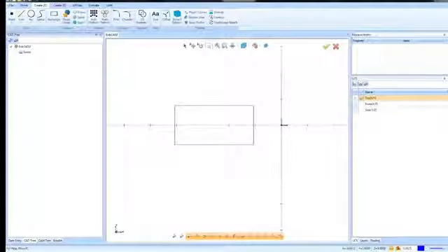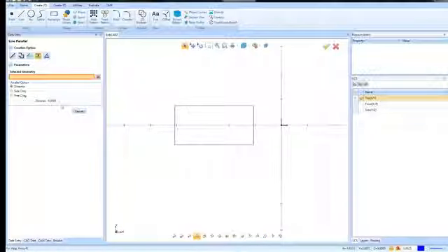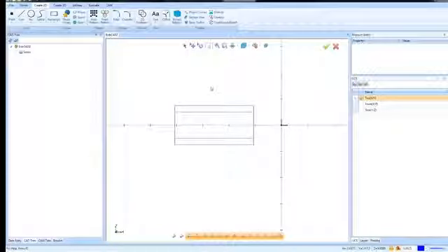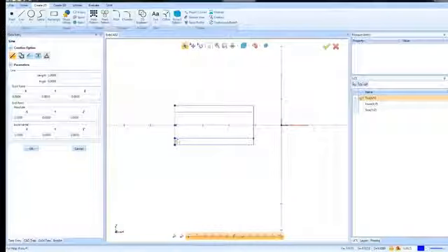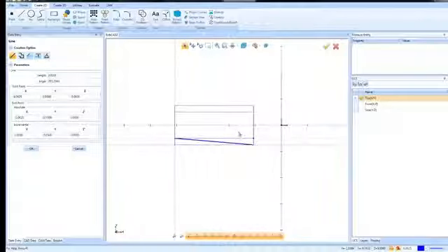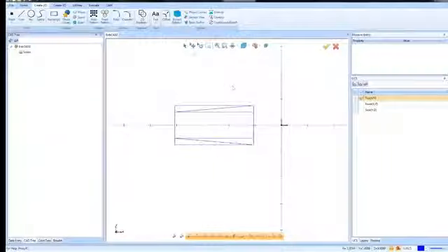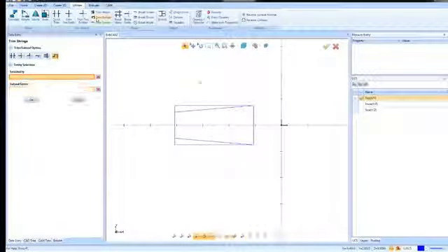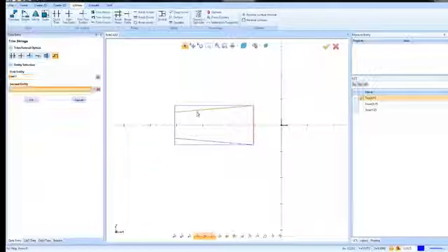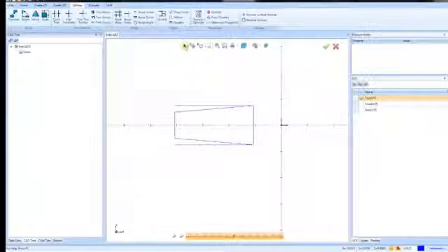And then what I want to do is I'm just going to do line parallel, a 1/4 inch this way, a 1/4 inch that way. And then I'm just going to use that as some construction geometry in order to change the design a little bit to add a little more character to it. All right, so we'll get rid of these entities here. And from here, we're going to trim this up. So I'm going to use Utilities, Trim Strings. So we'll go here to here to here to here and to there. So that gets that all trimmed up.